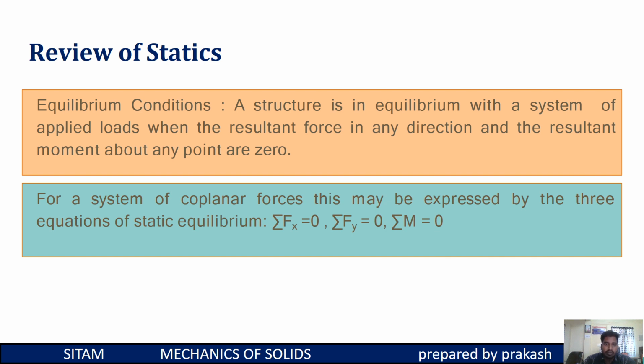In that condition, the resultant forces and the applied loads are equal. For a system of coplanar forces, this may be expressed by the three equations of static equilibrium: the sum of forces along the x direction is equal to 0, the sum of forces along the y direction is equal to 0, and the sum of moments about the body is equal to 0.